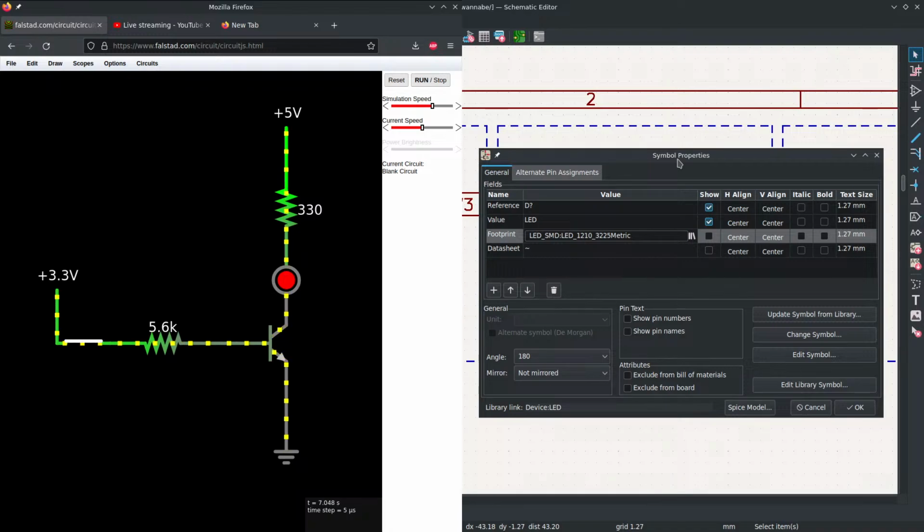It's the same thing, you're just choosing the pad. The hand solder version just has larger pads to make it easier to get a soldering iron on them. The ones for manufacturer or automated installation have pads only slightly bigger than the component you're putting on there, so there's not really that much room to move around. That makes sense.